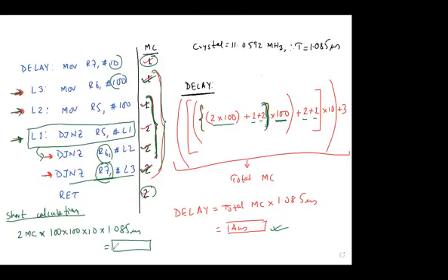This is known as a short calculation. What we are doing is neglecting the rest of the machine cycles. We are simply using the innermost loop, which is executed the most number of times. So we just write how many machine cycles we need. How many times will it be repeated? It will totally depend on the number of levels. We have got 3 levels. Who is controlling these 3 levels? R5, R6, and R7. So simply multiply R5, R6, and R7. Then you multiply your time period. Whatever you get is your answer. This is known as a short calculation, and you will use it when you want to design a specific time delay.